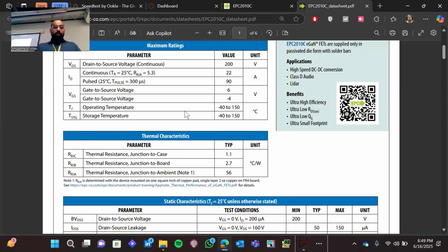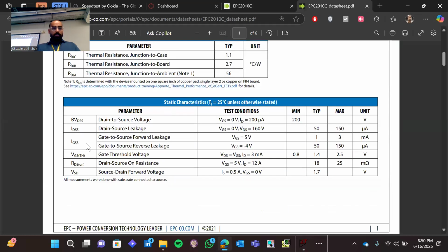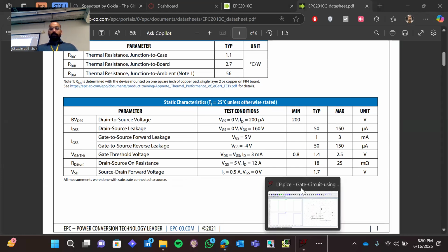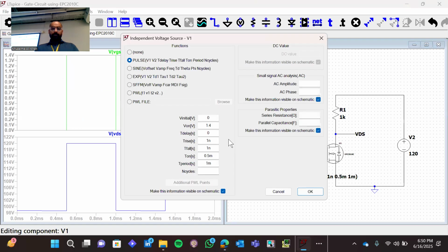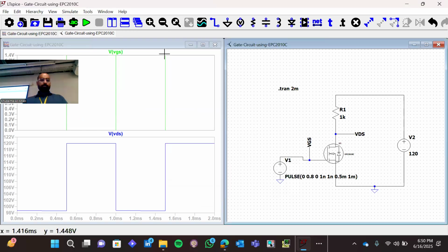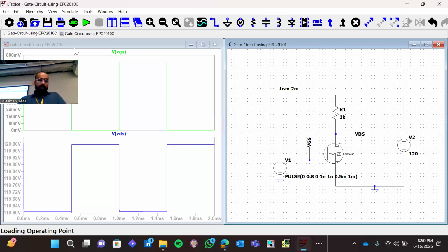So यहाँ पे you saw the threshold voltage to basically turn it on is 1.4, right? 0.8 is the minimum over here. ठीक है? Let's see 0.8 over here. Let's see 0.8. ठीक है, it is switching on and off. ठीक है? At 0.8 also.